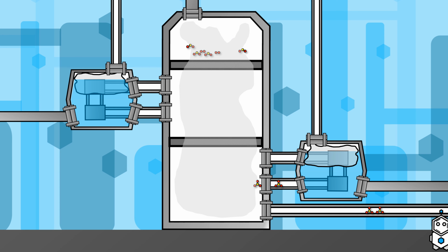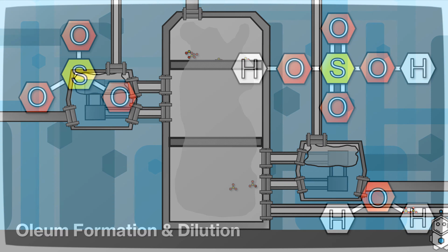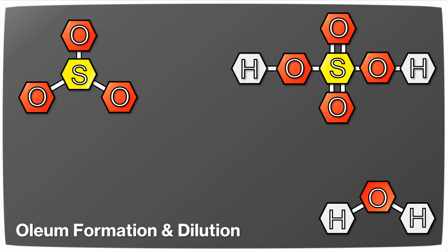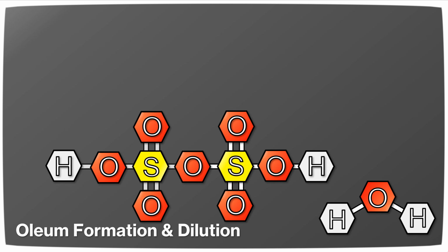The reaction is carried out at 450 degrees Celsius to balance the rate of reaction and the yield. Again, this process produces heat. The Benzenes recover this energy using heat exchangers. The final part of the process involves 2 stages. Firstly, reacting the sulphur trioxide with a highly concentrated stream of pre-made sulphuric acid to form oleum.